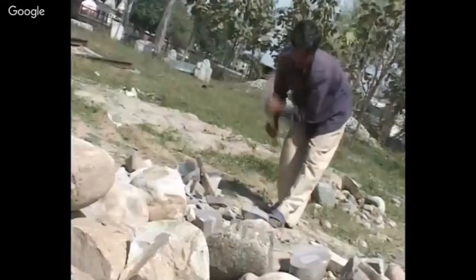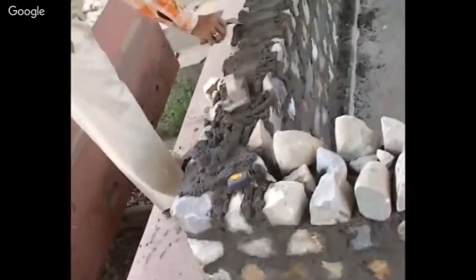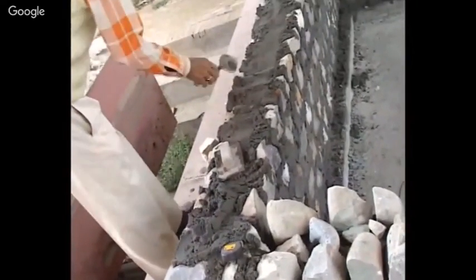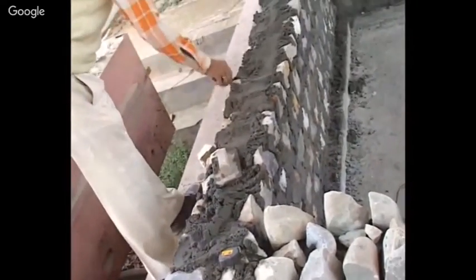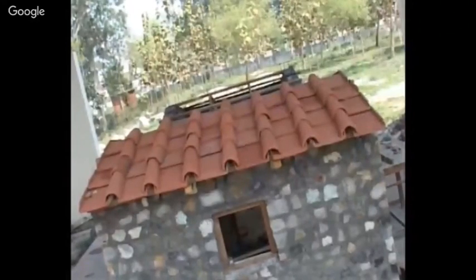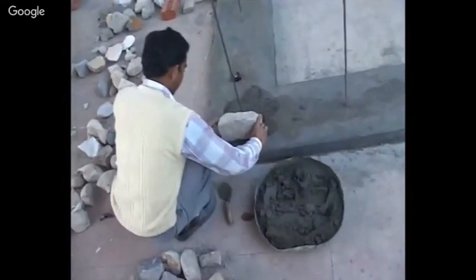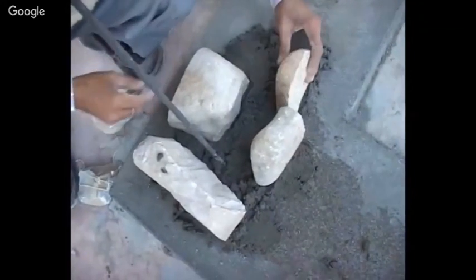Two half-scale single-room models are constructed on the shock table. As before, the first model is constructed using traditional construction techniques used by the common man. While constructing the earthquake-resistant model, features like the corner steel and the jam steel around the openings are placed so as to develop tensile strength.